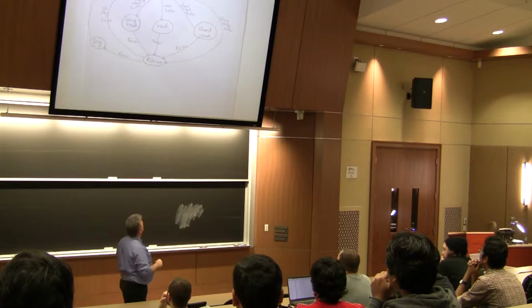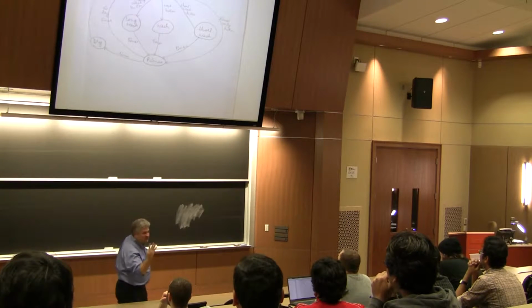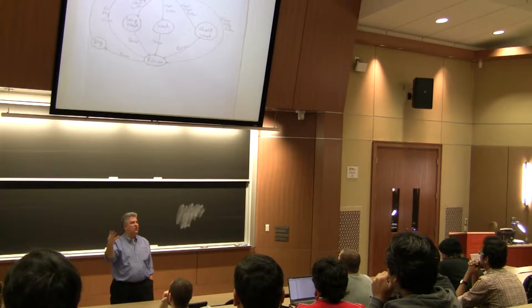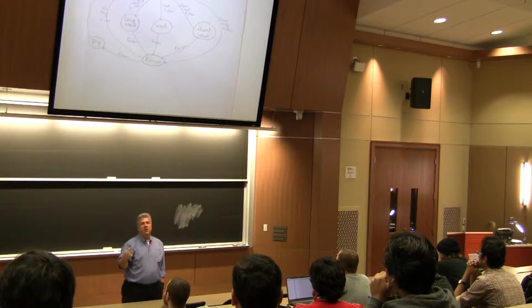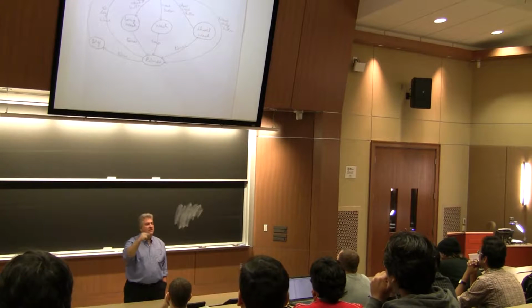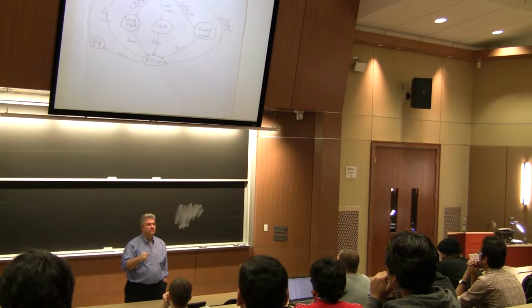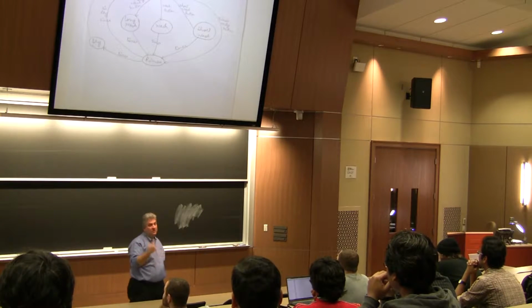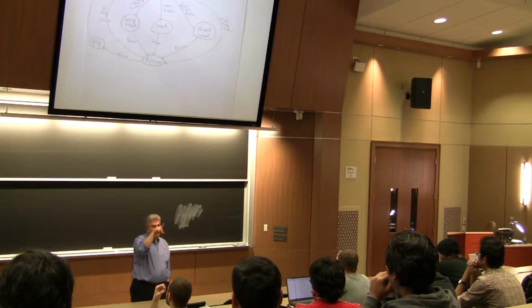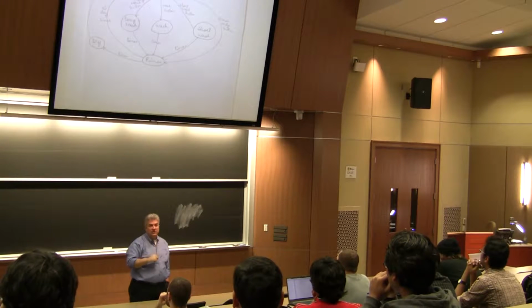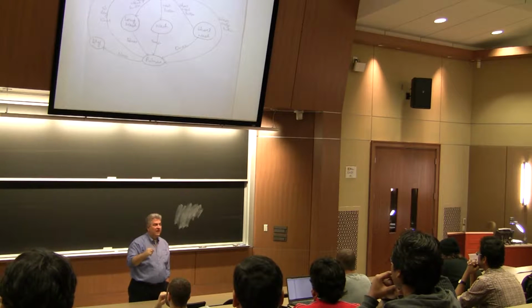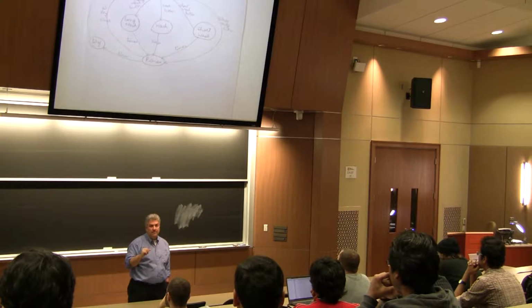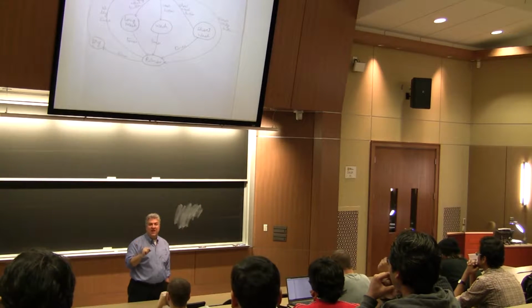All right? So from this respect, since we say the first 4 buttons will start something, what will most likely that button be tied to inside the microprocessor? An interrupt. Most likely it will be tied to an interrupt. Not necessarily all the time. For example, your idle state might be sitting there just checking the buttons again and again and again. And when one of them finally comes in, then you start. Kind of a waste of electricity there.